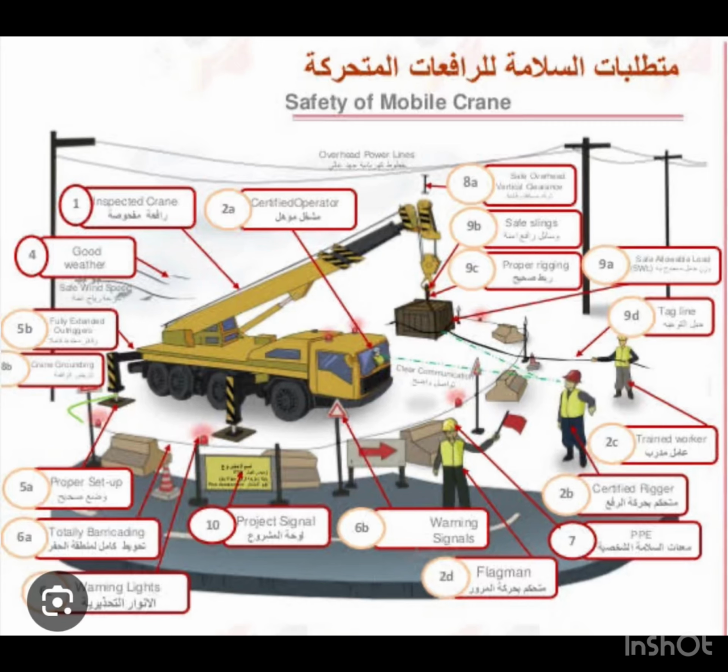The load weight is confirmed and is within the safe working limits of the crane. Ensure the swing radius is barricaded and no unauthorized entry into the lifting zone. Wind speed up to 32 km per hour is permissible while lifting. Ensure there is a rigging plan for all critical lifting activity. Make sure safe lifting procedure is being followed.